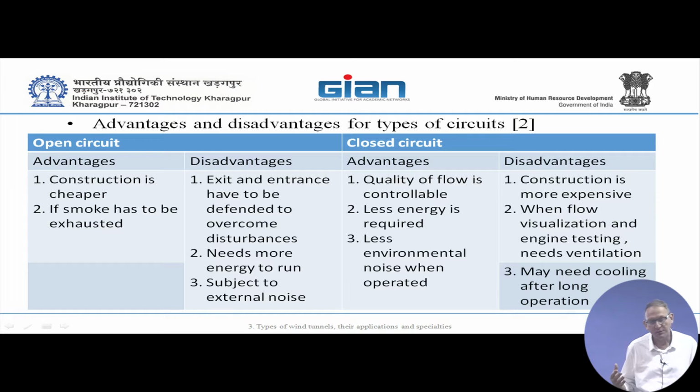So this is a disadvantage. Then, of course, we had the doors to open and ventilate the tunnel level. To start with, you have to ventilate it after some time. Otherwise, you don't see anything. And also, you may need cooling. Once the air is circulating, energy is absorbed by the flow, and the temperature is rising slowly. So you may need to cool it, depending on the velocity and the heat flux from the tunnel.